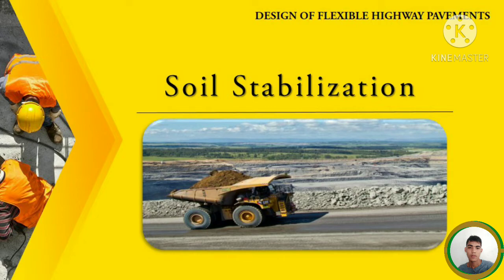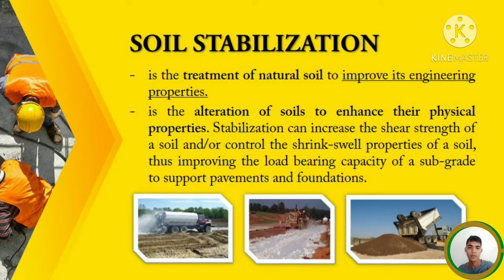We're done with the structural components of flexible pavements. That means that soil stabilization is now taking place. Let's go directly to the definition of soil stabilization. Soil stabilization is the treatment of natural soil to improve its engineering properties. It is the alteration of soils to enhance their physical properties. The stabilization can increase the strength of a soil and/or control the shrink and swell properties of a soil, thus improving the load-bearing capacity of a subgrade to support pavements and foundations.